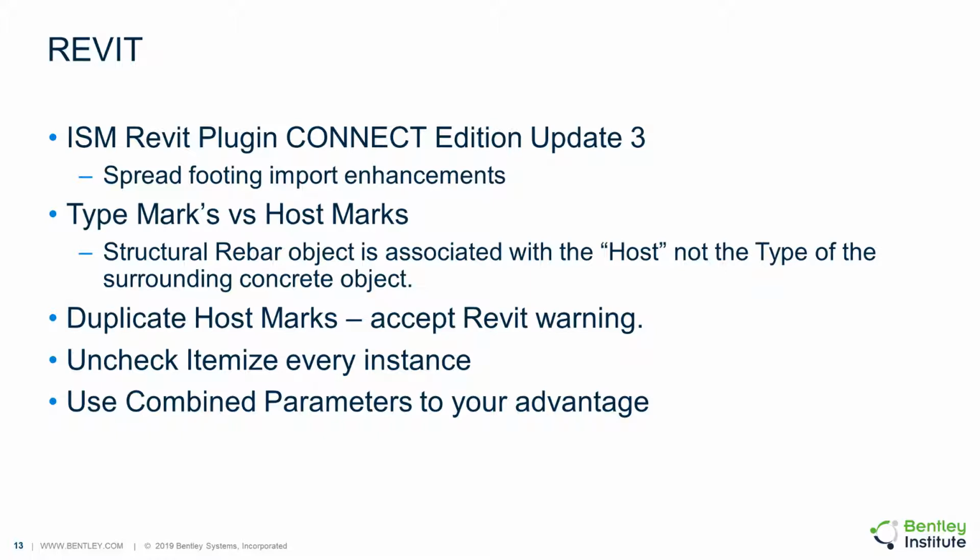Other things to be mindful of are in the schedule properties, you want to uncheck itemize every instance. So you don't want every single instance occupying a row of your foundation schedule. You want that to be grouped some way, and a way to do that is to uncheck itemize every instance.